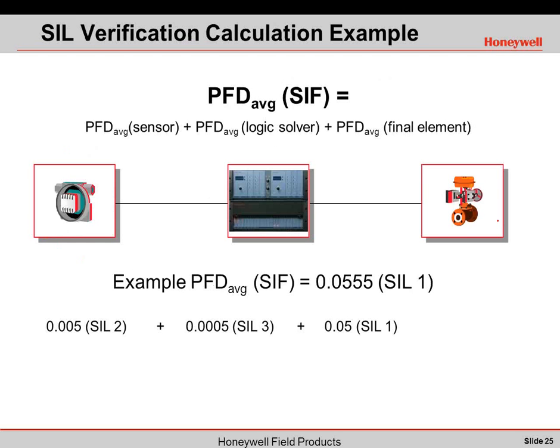So let's take a look at a couple of systems. Here we have a system that's a single sensor, a logic solver, and a valve. If this is a safety system, we can buy sensors that are SIL rated. The rating on the individual sensors, or in this case on the logic solver, are typically done by TUV.